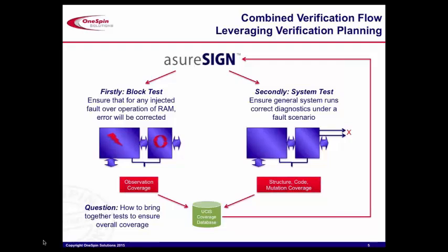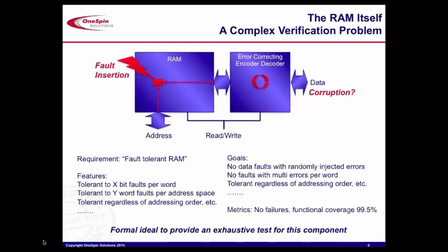So the first thing is to test the component. We would argue this can be done, of course, with simulation or with formal verification or a combination thereof. In this particular example, the company doing this used formal, and what they essentially did is create assertions that would specify, and actually the assertion isn't that hard in this case, essentially for the address range that needs to be tested: let's check all the possible data values and all the possible ways that the data values may be encoded and decoded.